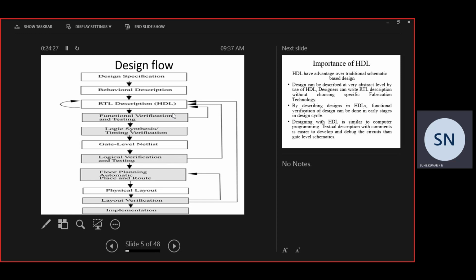For B equal to 1, this will be in off state. What is the output over here? Because the VDD is connected in parallel, even though it will not reach here through this path because it is in off state and acting like an open, here it will be a closed path because it is on. So VDD will come here and it will be coming over here, and the output will be 0. So the second case is also verified.